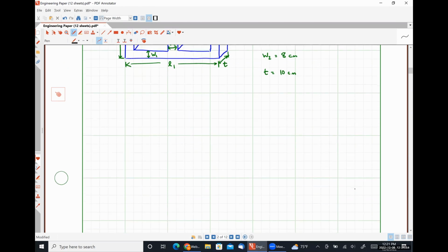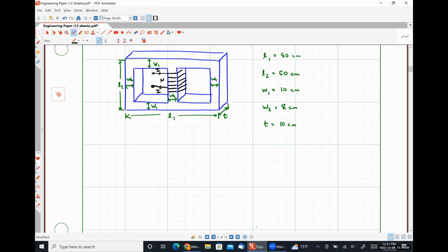Okay. All right, so I am going to look at this structure as if it were an electrical circuit effectively. So I'm going to start with that middle area where my coil is. And so I'm going to see the reluctance of the middle, and I'm going to put that in series with my MMF. So that's the middle branch.